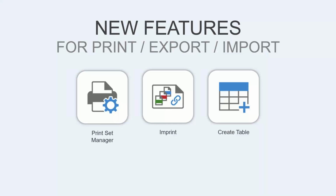The print set manager, if you're familiar with the Naviate publish feature that already existed, you know that you're able to go into that feature and modify your Revit view sheet sets. Well, we've just created a standalone feature for that you can directly access in the toolbar, and you can create, modify, or delete your Revit view sheet sets.